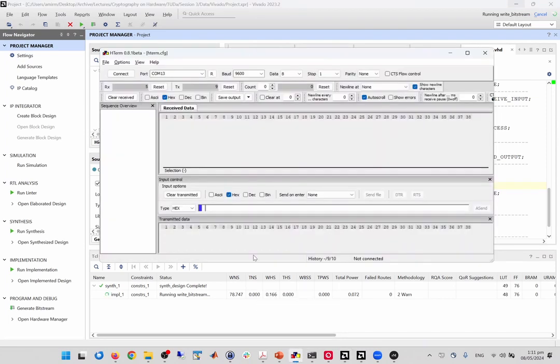I can show you something now. The FPGA is not configured, it's just powered in. And then I connect to the COM port and I send something. You see, I send something, I receive nothing. Here is send. If I receive something, it should appear here in receive data. Send, nothing, because it's not configured as I want.